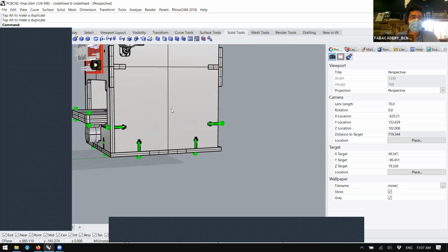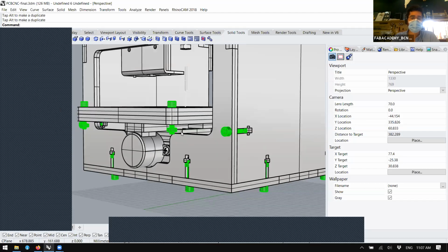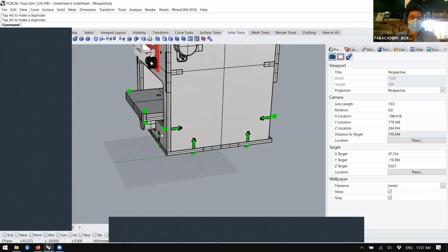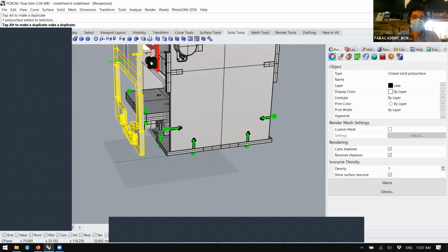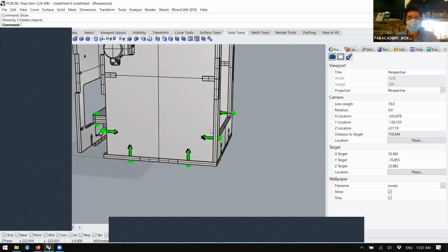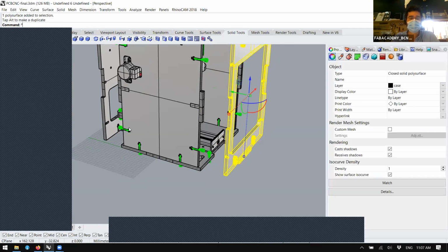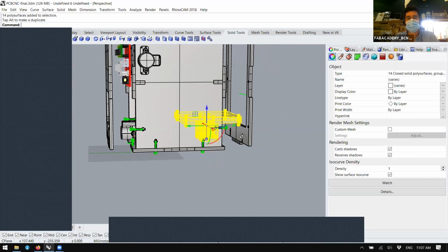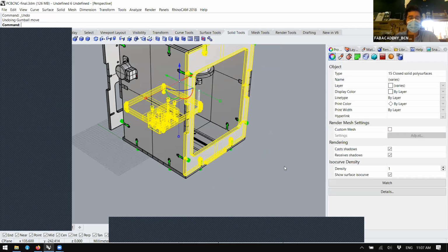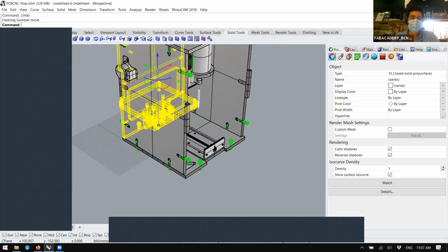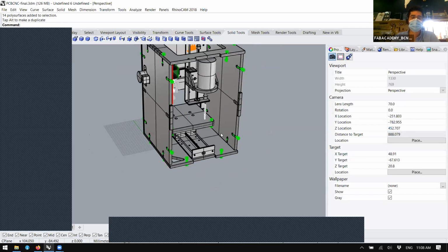For that, the platform, while you are using it, is moving out of the machine. A lot of machines don't use this because they don't need to reduce the footprint, and what they do is just make the frame much bigger. So instead of having the frame constrained to the slider, it is constrained to the working size. So when you move the machine, the platform never gets out. That's another option, and maybe you can make a fork of the machine like this. We just did it this way to keep everything as small as possible and to reduce the total material cost of the machine.